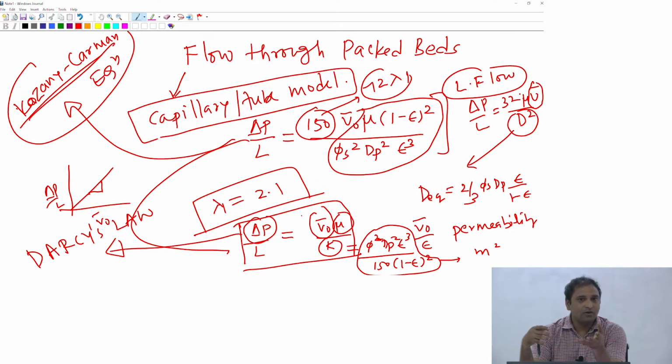sand, for example. Everywhere people use the flow through packed bed concept to extract some meaningful parameters. We're also going to look at cases where this Kozeny-Kármán equation that we have developed can be used for basic characterization of the particles itself, which we're going to look at a little later. That's for the laminar flow conditions.